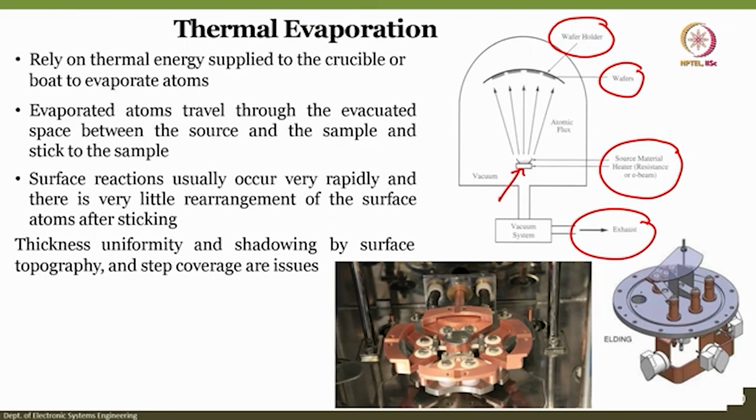Surface reaction usually occurs very rapidly and there is very little time for rearrangement. You see, we came back to the same point: there is very little time for rearrangement of the surface atoms after sticking. The thickness uniformity, shadowing by surface topography, as well as step coverage are the issues.